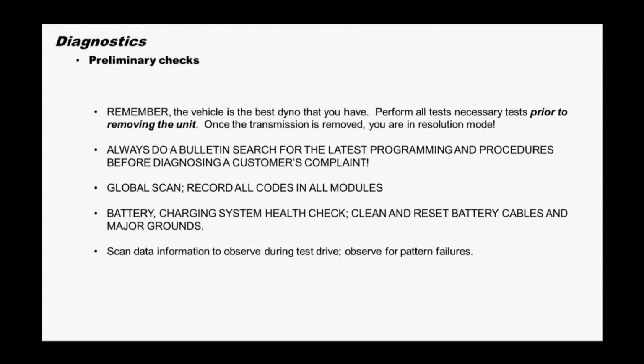On the road test, make sure you have a scan tool hooked up and recording a movie on the scan tool. Snap-on scanners are recording whenever the scanner is plugged in. This is very helpful because when the problem happens on a road test, you can safely pull over and save the recordings for when you get back to the shop.